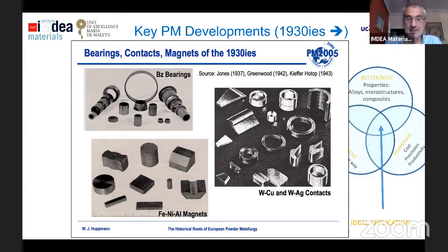the bearings, which I used as an example in my previous lecture for beginners, as a combination of the three main fields of application. Bearings are a porous material that is really cheap to produce by powder metallurgy, which combines the best possible properties for this application, and it is also the only way to produce them, because in bearings we have a porous material with a very well-controlled porosity inside in order to capture the oil for self-lubricating bearings, with a microstructure fully optimized for these applications.